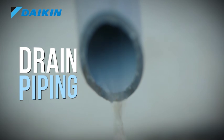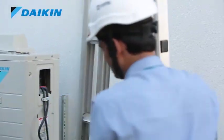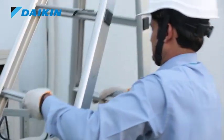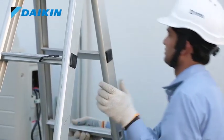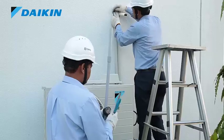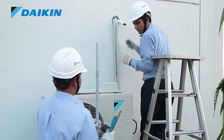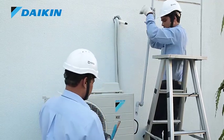Drain piping. Positioning and fitting the drain piping is very important. The drain pipe route should be clear, and do take extra precaution while carrying out the drain pipe work. Ensure that the drain pipe should not terminate at any place where there is any foul smell.